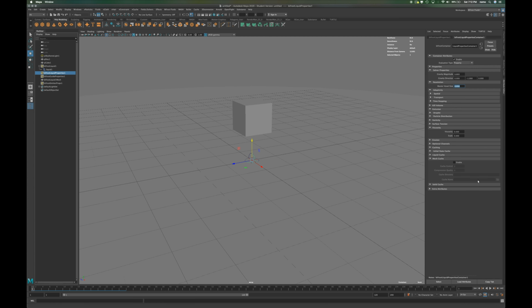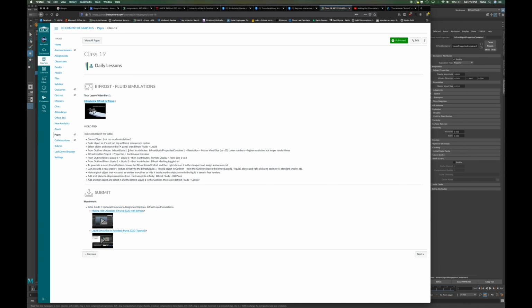They disappeared on the preview there. But if I went like 0.03, let's see if they come back. No. Oh, maybe. No, it's still not coming back. But 0.05, let's stick with that. If you go too low of a number, it's almost like the resolution. You're going to have a more fluid liquid, but you're going to pay for it in render time. All right, so that's the first step. Then let's just go look at this list one more time. So we've brought that down to 0.05, like I put in here. Lower numbers equal higher res, but longer render times.